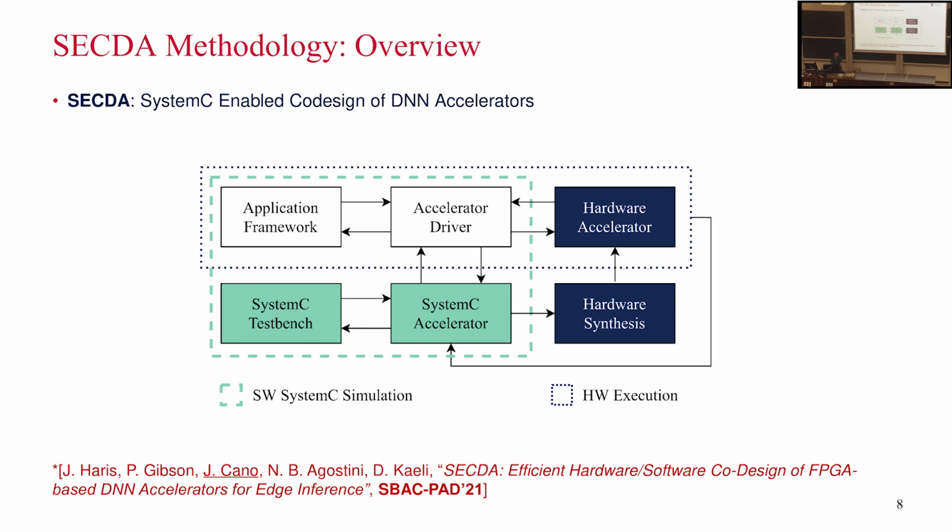So what we do is have this alternative loop here in green. We iterate, develop and tune the accelerator only in simulation, and eventually we do the synthesis to measure real performance, real memory transfer times, and so on, just to make sure that what we are designing in simulation actually matches real performance on hardware. That's the idea: combining these two loops.